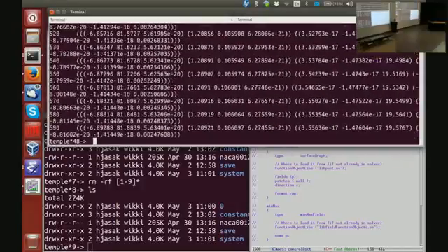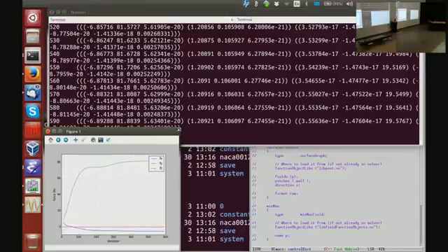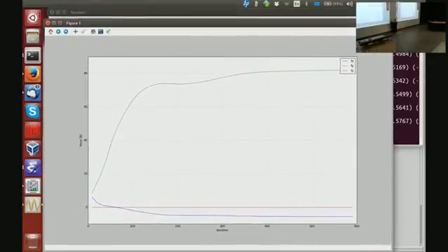With Foam Extend I have a little tool called plot forces, which will create an XY graph of your forces by removing all these brackets. This is usually a good measure of convergence. So around here, say 400 iterations, my force is pretty well stabilized, and I can declare that my simulation has converged. Also, this is 2D, so the Z force will be 0.